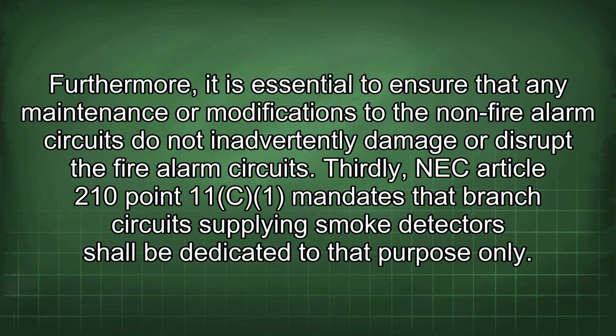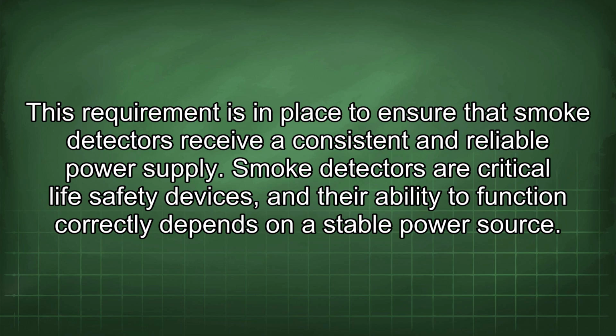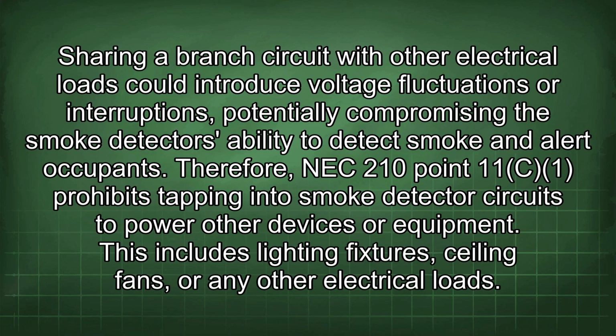Thirdly, NEC Article 210.11(c) mandates that branch circuits supplying smoke detectors shall be dedicated to that purpose only. This requirement is in place to ensure that smoke detectors receive a consistent and reliable power supply. Smoke detectors are critical life safety devices, and their ability to function correctly depends on a stable power source. Sharing a branch circuit with other electrical loads could introduce voltage fluctuations or interruptions, potentially compromising the smoke detector's ability to detect smoke and alert occupants.